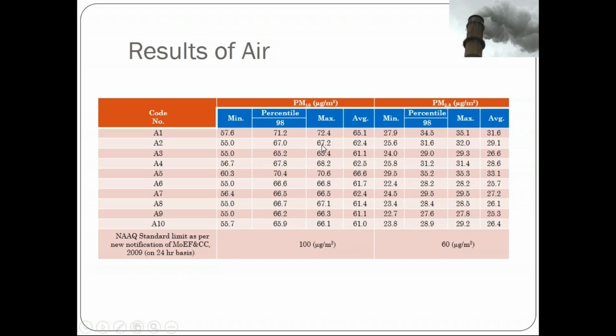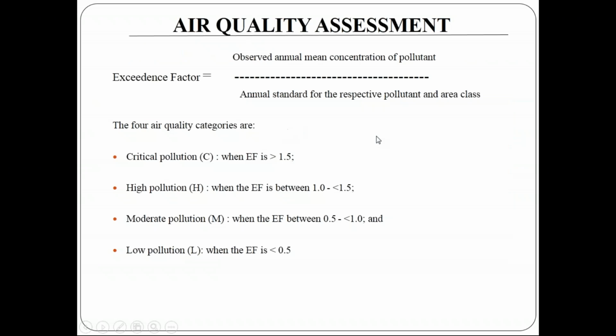So we need to run the GLC on the basis of the 90th percentile only, not minimum, not average, not max, because max is for a short period of time, but the 90th percentile is for 90 percent of the time interval. So we have to calculate, and we have to interpret the data. We have to compare the GLC data with the 90th percentile only.